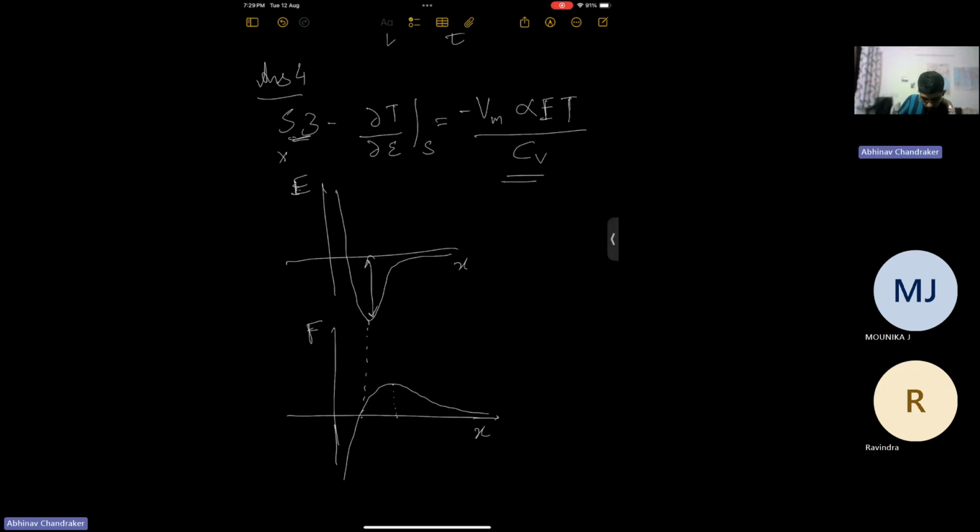So you will have to pull the atoms with a force equal to this value to take them apart, and the energy associated with the total breakage will be equal to, because finally the energy is zero at infinity, the depth of the well. So the larger the depth, the higher the sublimation temperature will be, since higher vibrational energy is required. So S4 is true.